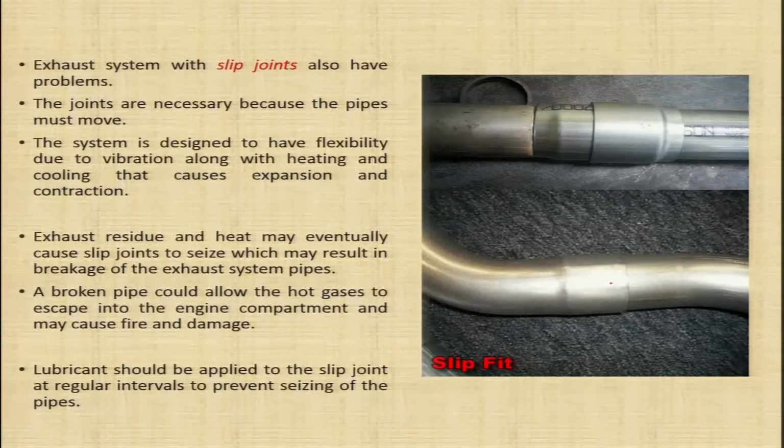The joints are necessary because the pipes must move. These slip joints are designed so that the system has flexibility due to vibration, and due to heating and cooling, because of which expansion and contraction of the metal takes place.